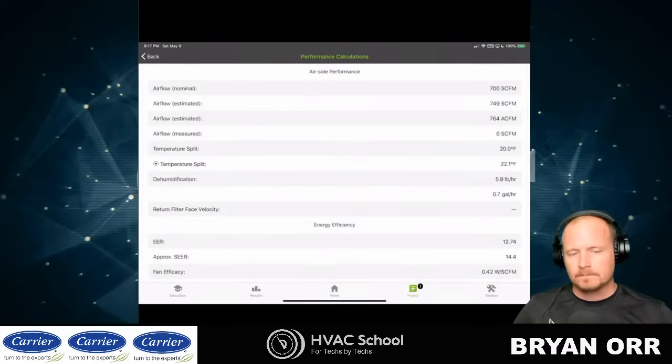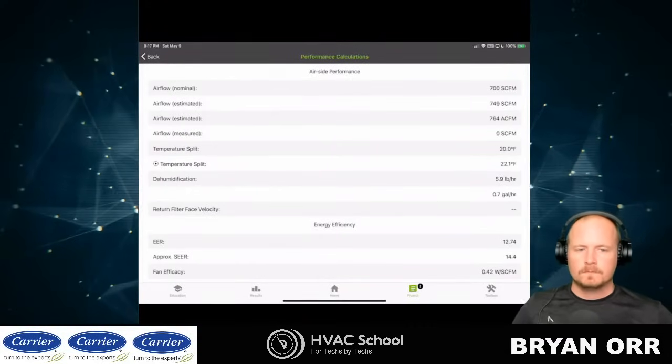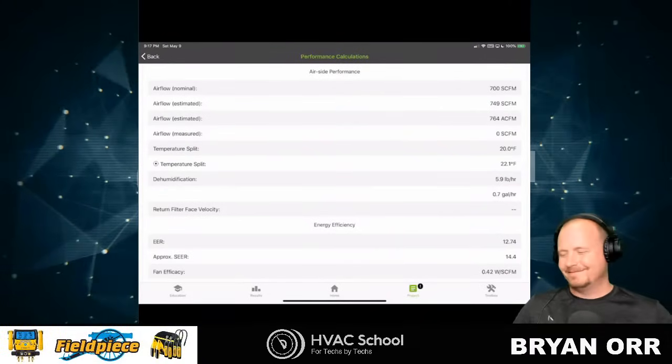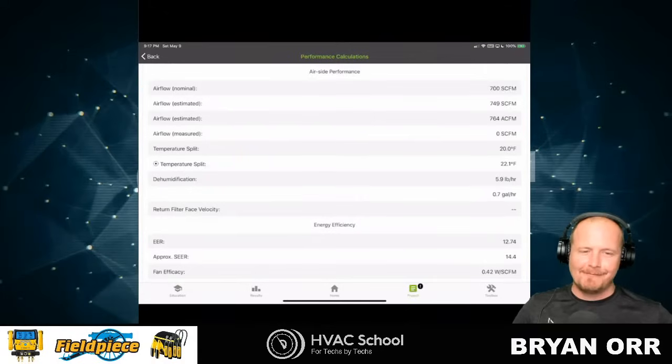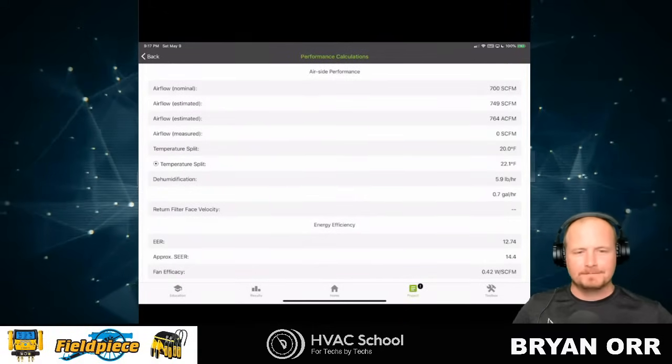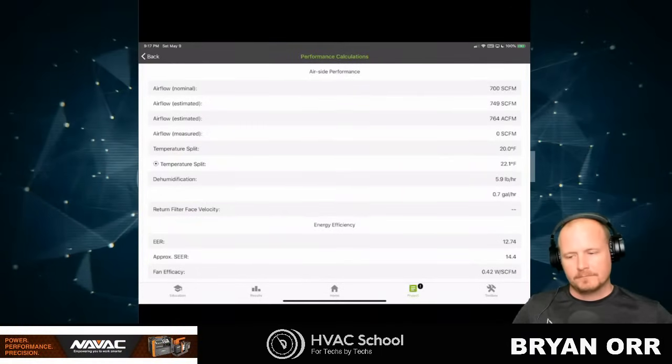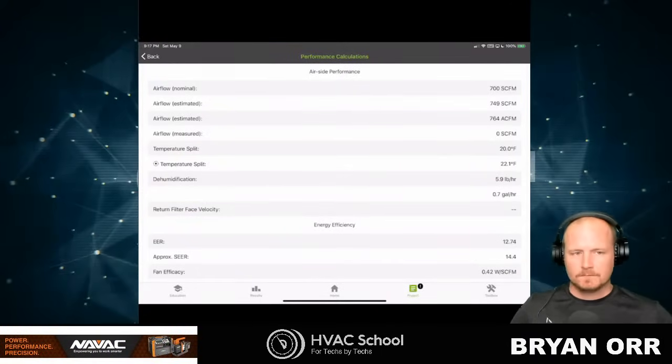Yeah, and there's even more interesting things. Some guys we found out just recently doing package rooftop units hired a bunch of young guys, and they were putting the liquid line probe on the discharge line. So now we can sense that in MeasureQuick, because that messes up all the calculations. But you don't think about those things until you start to look at bigger data and why people are getting weird readings out of your software.